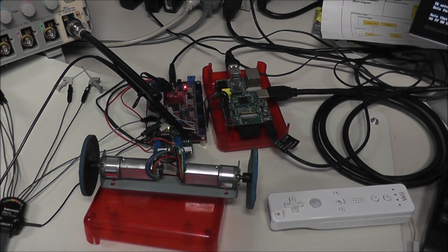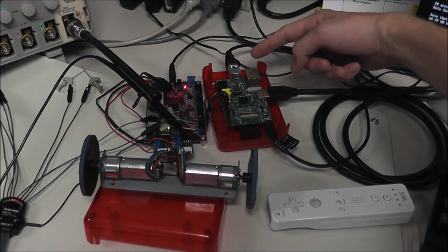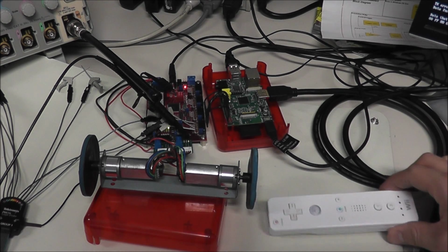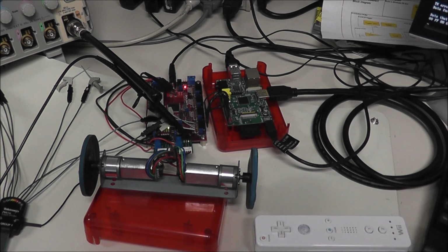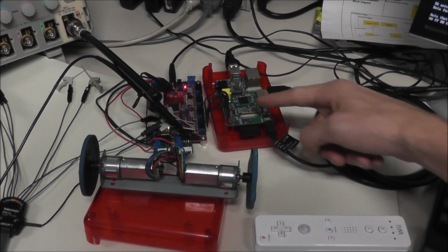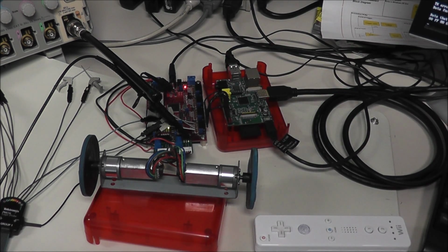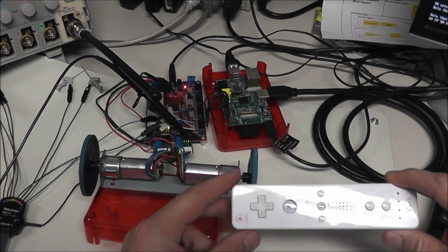I've got my Raspberry Pi, and attached to it I've got a USB Bluetooth dongle that I connect to my Wii controller through programming commands. This has a SPI connection on it that goes from the Raspberry Pi over to my Atmega 64 microcontroller, which is then going to output PWM waves to DC motors that are going to drive the speed. I'm going to demonstrate this, and then I'm going to show you on the MDO how to use it.